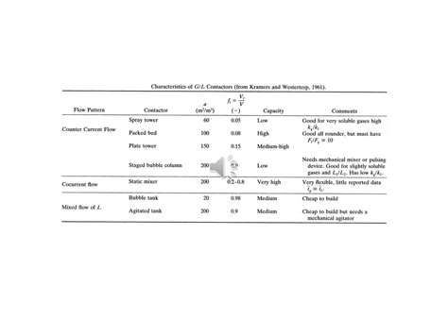And for a system with a lower Hatta number, we need a system which has large liquid holdup, because the liquid film is controlling, hence a high FL. And other comments are there on the table. You will notice that for average interfacial area, we have packed bed, plate tower, and staged bubble columns.